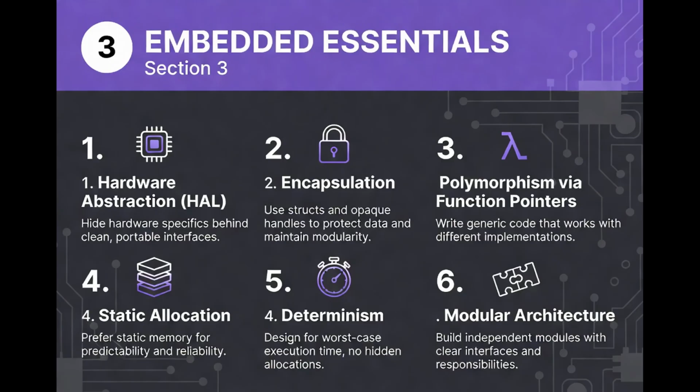Static allocation is the fourth essential component in embedded systems. Embedded systems usually prefer static memory allocations. Dynamic memory allocation can introduce fragmentation, non-deterministic latency, memory leaks, and unpredictable failures. Static memory improves reliability, timing determinism, and safety certification.